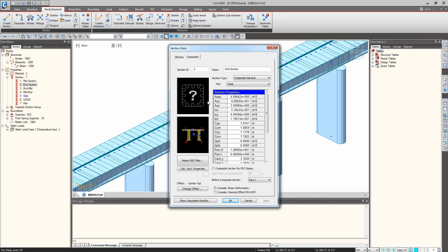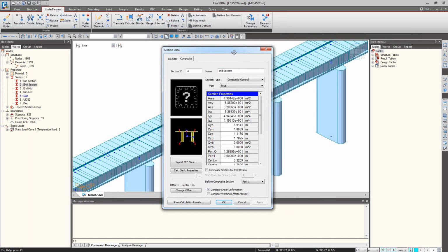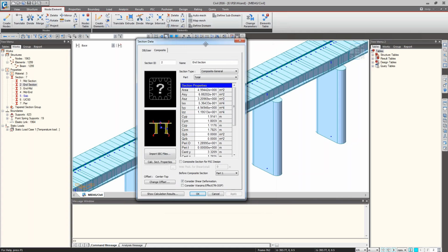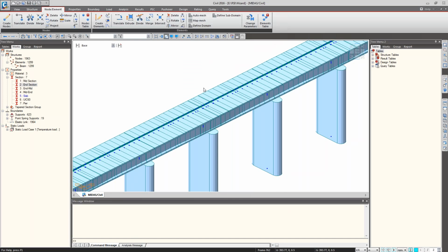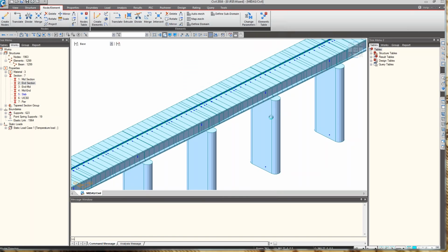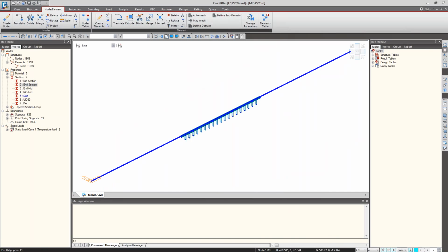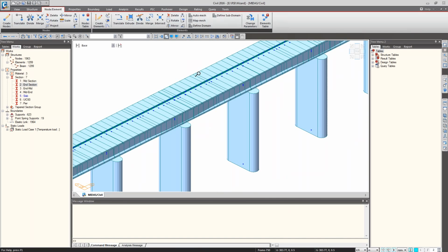People ask us what the applicability is and how it compares with the actual grillage model, wherein the behavior is different for different girders. This has been compared with the actual grillage model. Here it is just a line model connected to the rails. In a grillage model, the individual position of the rail will be connected and the axial deformations will be transferred differently to different girders.